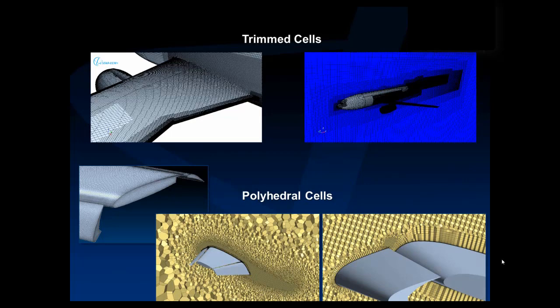Due to smooth growth behavior, polyhedral are typically preferred when aerodynamic coefficients are of key importance. Polyhedral also generally work better when large sweeps and flow directions such as angle of attack and side slip are used, due to the pseudo-random orientation of the faces. If a single or small variation of flow direction is desired, a trimmer mesh with the grid lines aligned to the flow often provides the most efficient approach to getting good answers.